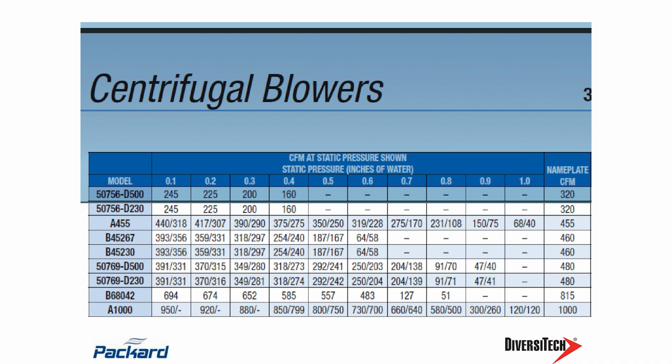Why not? Because when you install that blower into an application, now you're going to introduce static pressure. And when you introduce static pressure, you're going to restrict air. And let's say that I have an application requiring 0.4 inches of water column. Well, now all of a sudden, I'm only getting 850. That happens to be a 2-speed blower. That's why we see 2 different numbers in there. But if I'm operating this on high with 0.4 inches of static, the air I'm going to get is 850 CFM.